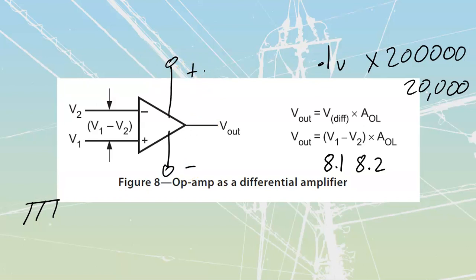We're going to use these things in a lot of cases where we're doing monitoring. A great example of this would be checking battery cells, if I had a very large set of industrial power inverter cells where we take power and stick it onto a DC bus, and then I need to maintain these cells for an emergency ride through. What you want to do is monitor and make sure all these cells are going to be the same, because if some of them are at too high a value of voltage or too low or they get unstable, remember what happens from when we were looking at rectifiers.